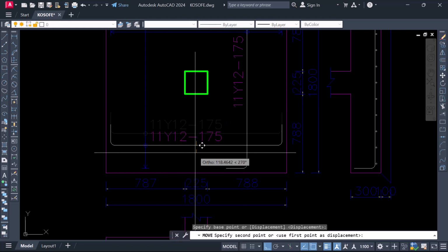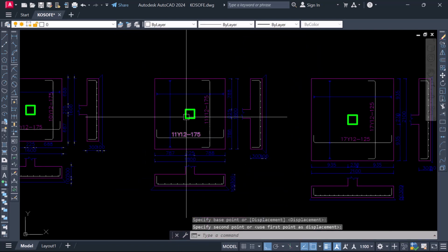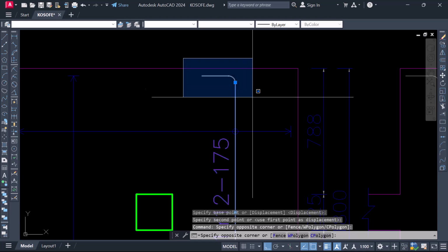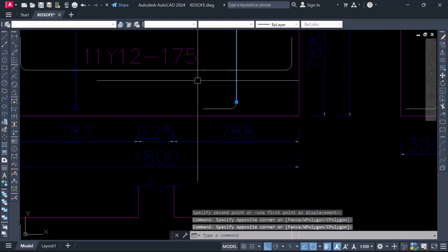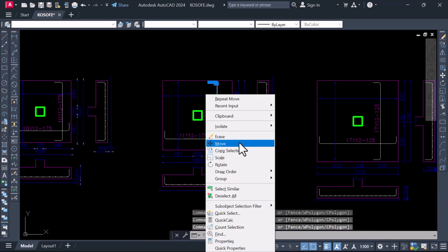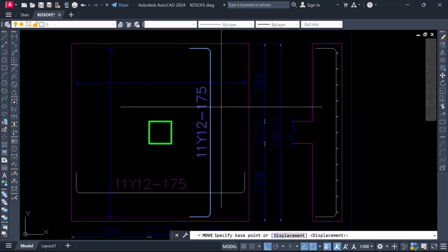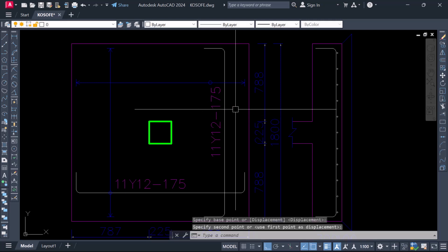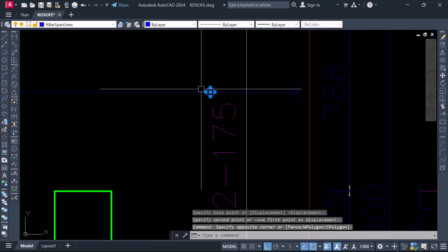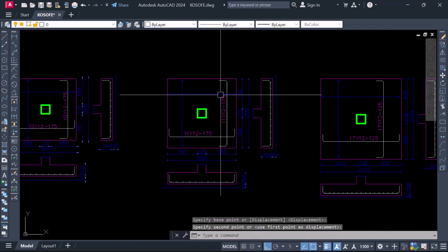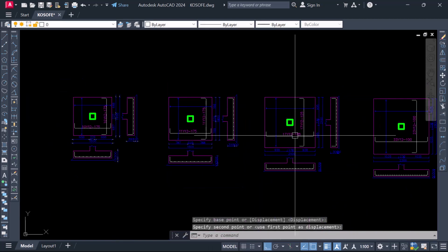What I'm trying to do is to separate the rebar because I want it to be well presentable. Detailing is a way by which you make the design, all the data that was generated from the structural software, outstanding in AutoCAD so that it can be properly read on site. So that's what I'm trying to do right here.